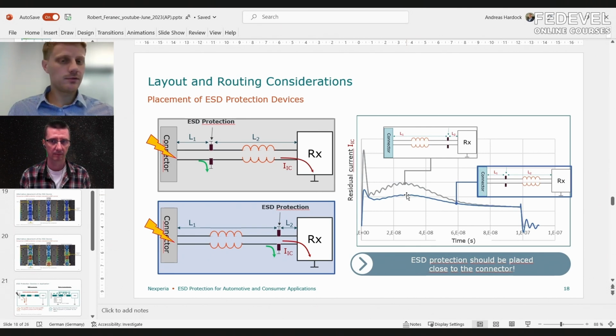Here it is pretty much the same. The source of your noise is the connector, the virtual source, because this is where you apply your pulse, and you want to filter it as soon as possible. Then even if you have the pulse in your ground plane, you are far away from the PHY, so the risk of trouble due to ground bouncing or ground currents is much more reduced.